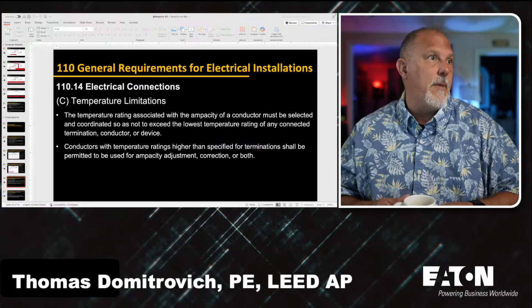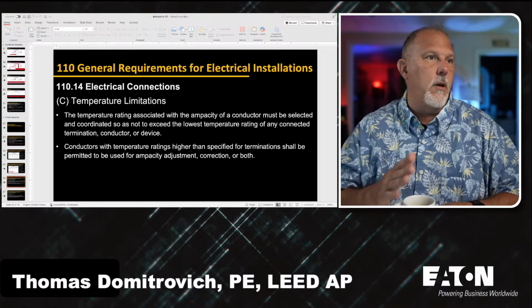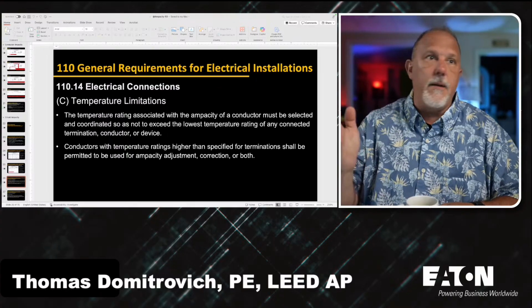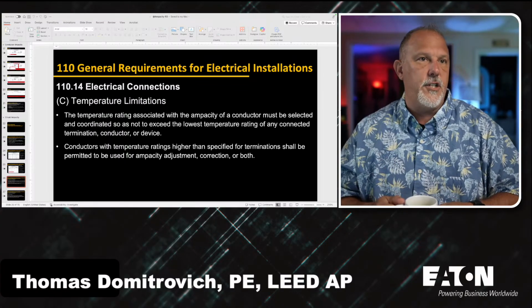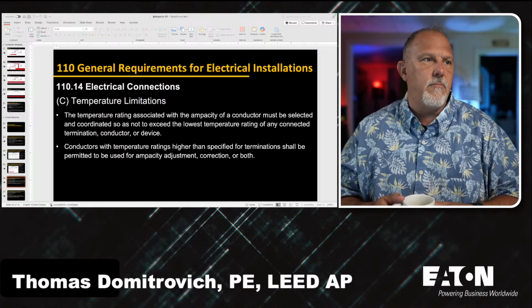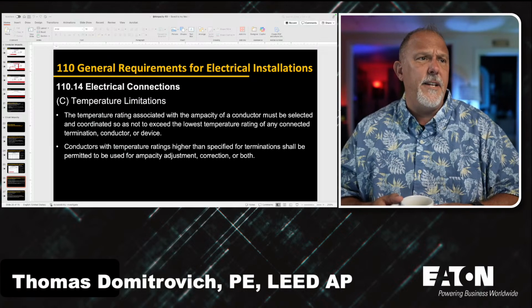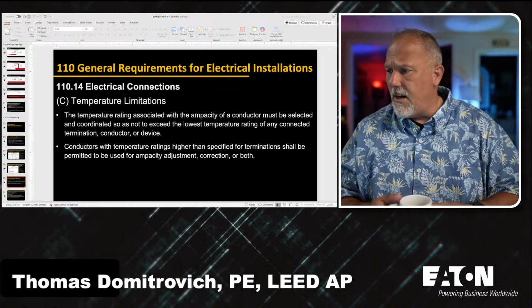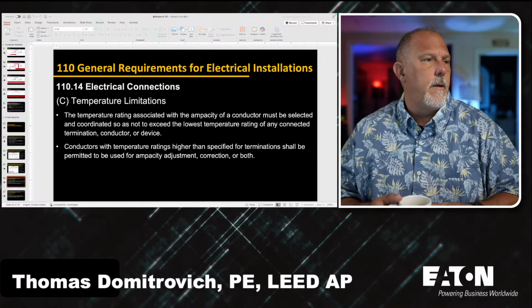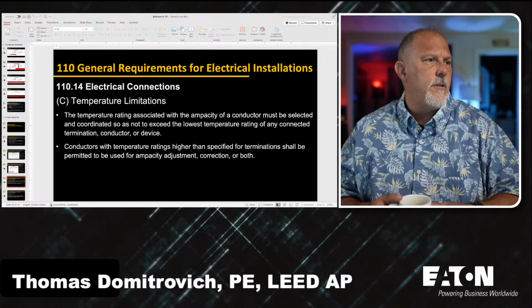That's the first change I would make to 110. 110.14 needs some work. So 110.14 parent text doesn't mean a hill of beans when it comes to ampacity calculations. Not at all. Talks about dissimilar metals, talks about finely stranded, talks about fluxes and solders. Terminals, connections of conductors to terminal parts.